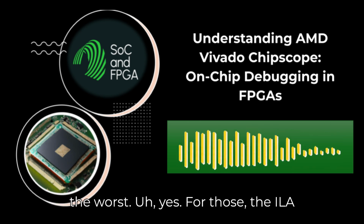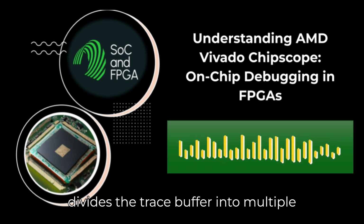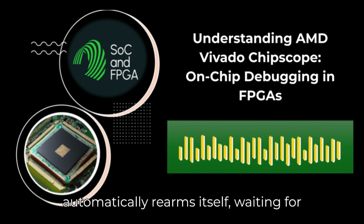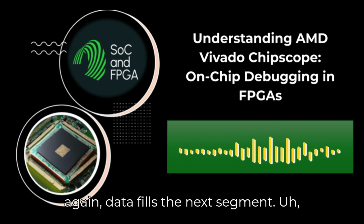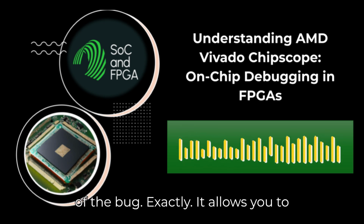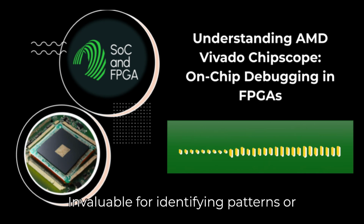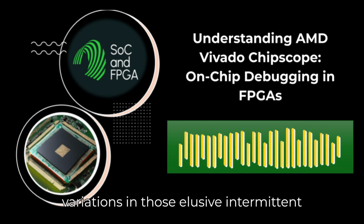Those are the worst. For those, the ILA offers capture windows. This effectively divides the trace buffer into multiple segments. When a trigger fires, data fills one segment. Then, the ILA automatically rearms itself, waiting for the trigger condition again. If it fires again, data fills the next segment. Ah, so you can capture multiple occurrences of the bug. Exactly. It allows you to view multiple distinct trigger events side by side in the waveform viewer. Invaluable for identifying patterns or variations in those elusive, intermittent failures.